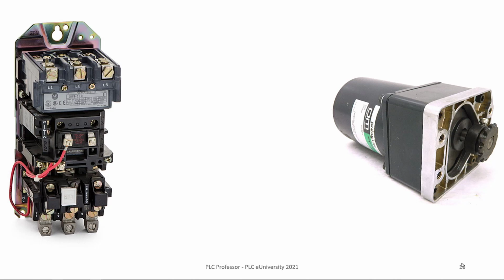You can see over to the left side, looks like a normally open contact with label 2 and 3, P2. That's an aux contact that you can use going back to the PLC to tell you whether the armature on this motor starter is energized or not. So this is just like an on-off switch for a three-phase motor.